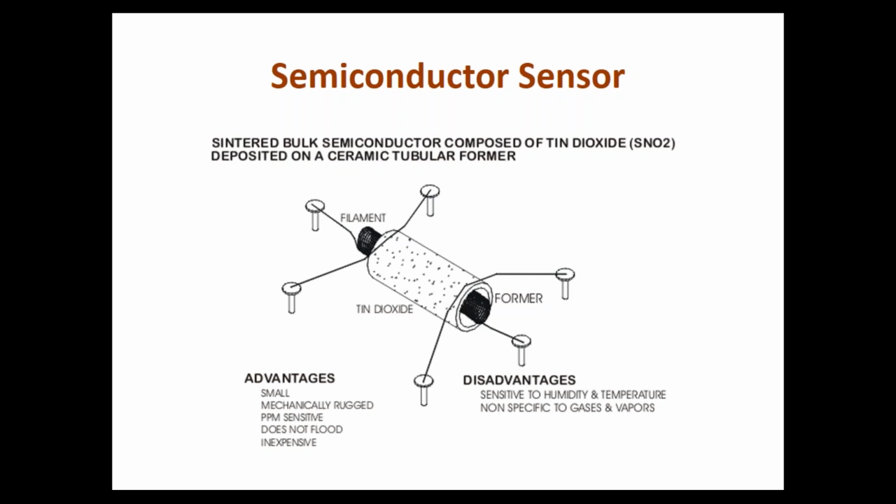A good example is we've had schools put it in boiler rooms where they just mount it in the boiler room. They never have to touch it, and this unit will last them 20, 25 years without changing the sensor. We put it in hospitals for ethylene oxide. We put it in parking garages, heated parking garages specifically, looking for carbon monoxide.